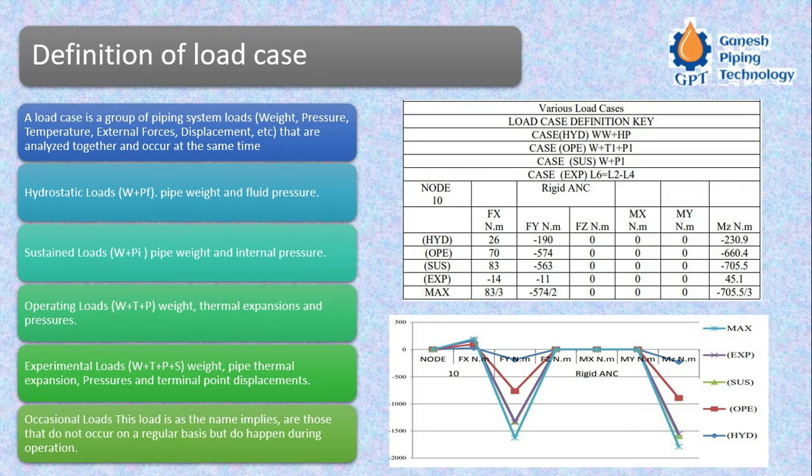We have completed the modeling and inputted all this information. Now the second stage is definition of the load. See, when we are doing the stress analysis, what we actually do is create a model virtually. Even then it has all the physical properties, the dimensions, and even the material properties of the real world pipe. And whatever fluid is inside that pipe, the density and all that we have to give, because based on that only we will know the weight of the pipe when it is filled with water. Water we are considering because the density is 1, so we get the maximum weight.